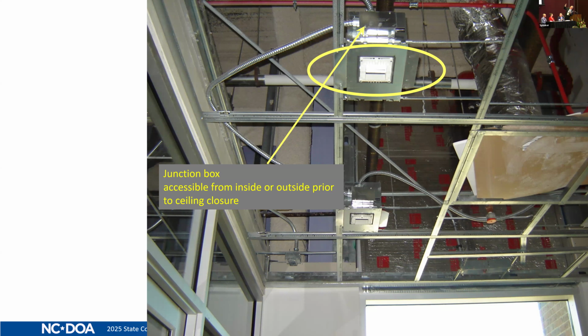So, is that box above it accessible? Since you can't go through the mud ring without moving part of the ceiling, it means you're going to have some way to get above the ceiling. You're going to add a 2x2 access door next to every one of these nice little fixtures that had only a 1x2 inch opening in it. What is your plan?